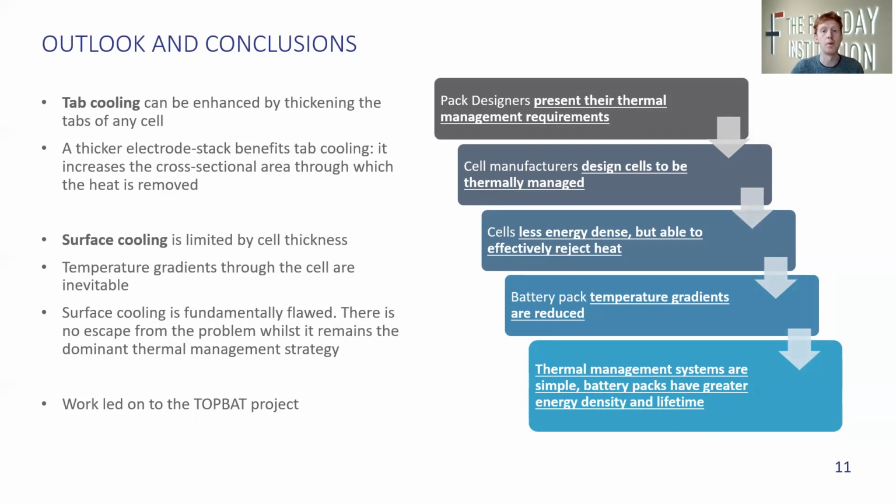Thermal management can no longer be ignored in favor of energy density optimization. A cell designed to be thermally managed will have a slightly lower energy density, but this can be made up many times over at pack level with more effective thermal management systems. Furthermore, a cell designed to be thermally managed will incur smaller temperature gradients, and this will reduce the degradation rate of the cell over its lifetime.